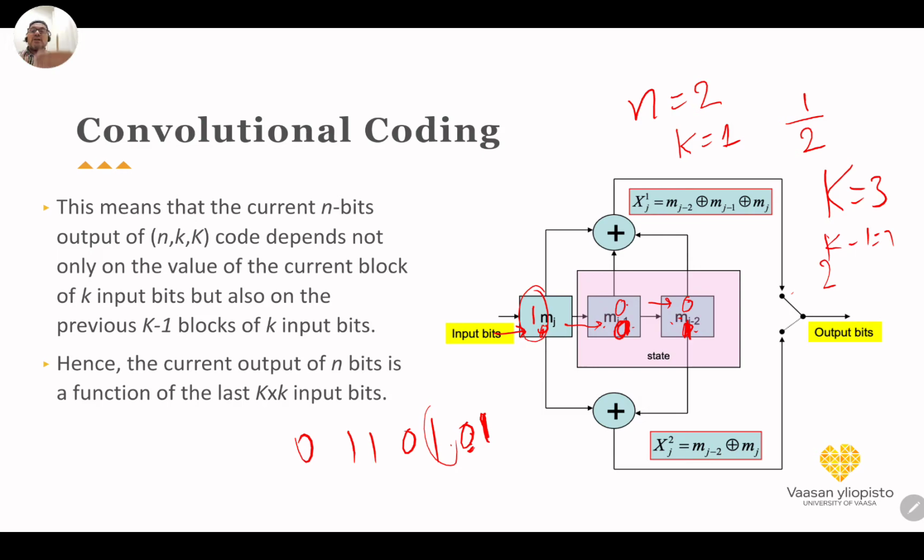So if there is a truncation in the data with a certain percentage, we would still be able to retrieve the information bits with some degradation. And we can also use this distribution, especially when we have states with many more previous bits. It is called space-time coding, as we will describe later when we talk about MIMO antennas.